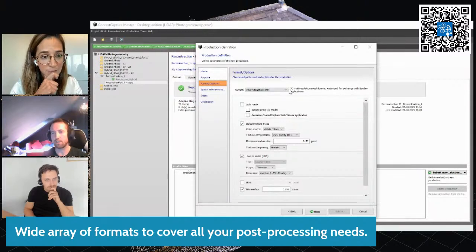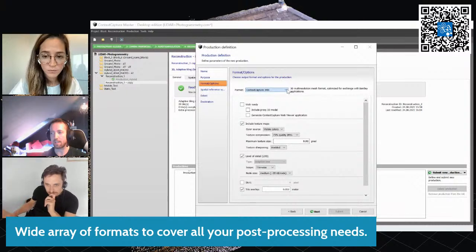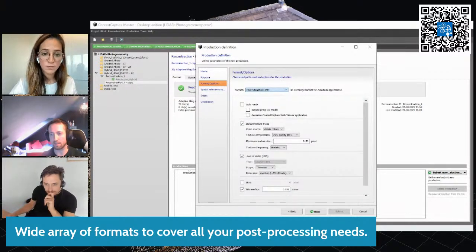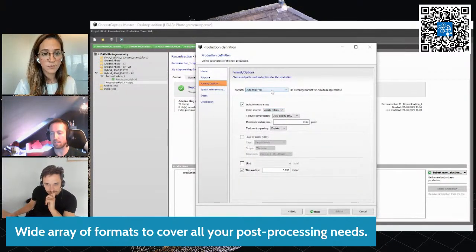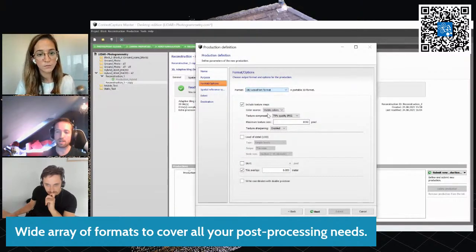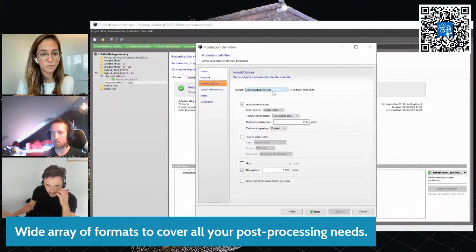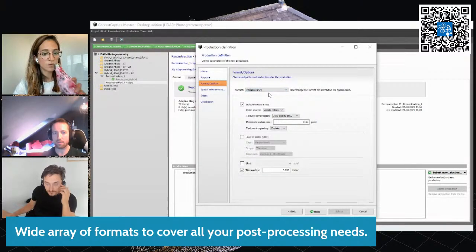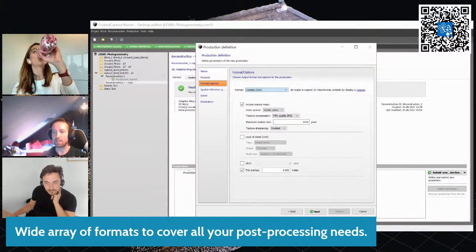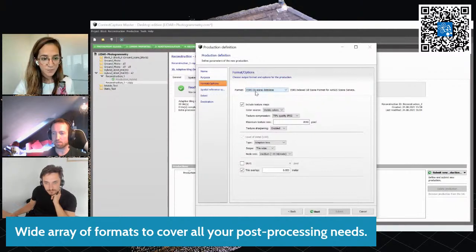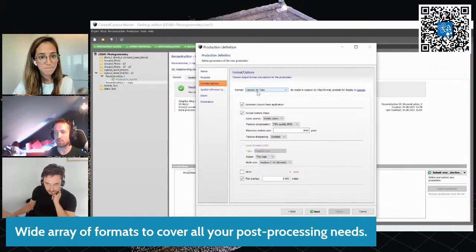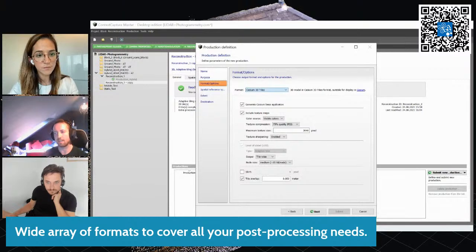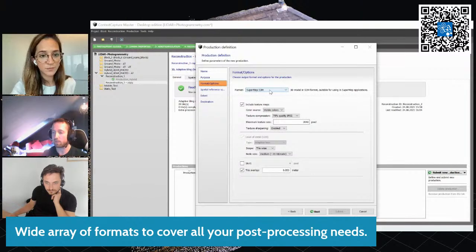We won't limit you to just Bentley formats. Obviously, we would still push the Bentley formats, which are 3MX and 3SM. They're multi-resolution, so if you're using a large data set, when you zoom in you get more detail, zoom out, less detail. But we can produce to all your AutoCAD stuff, your FBX, your OBJ, even 3D printing we can go towards that. Cesium, it's no problem at all. I'll keep it short, there's a lot of different settings. You can see below, a lot of the models are WebGL compatible, so if you want to throw them on a web server and display them online, just drop them in.